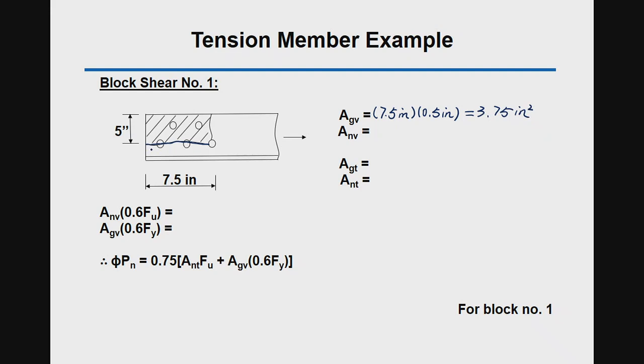And the net shear area, just use the gross shear area subtracted by the hole area, right?